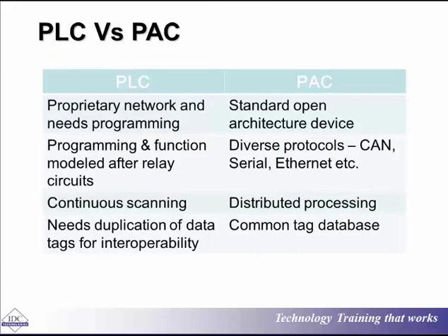The PLCs tend to have proprietary programming, whereas the PAC tends to have open programming, basically going for the computing type of languages. The PLC systems and programming tend to be based around relay logic or relay circuitry, whereas the other one tends to have far greater flexibility and, instead of continuous scanning, it has distributed processing.